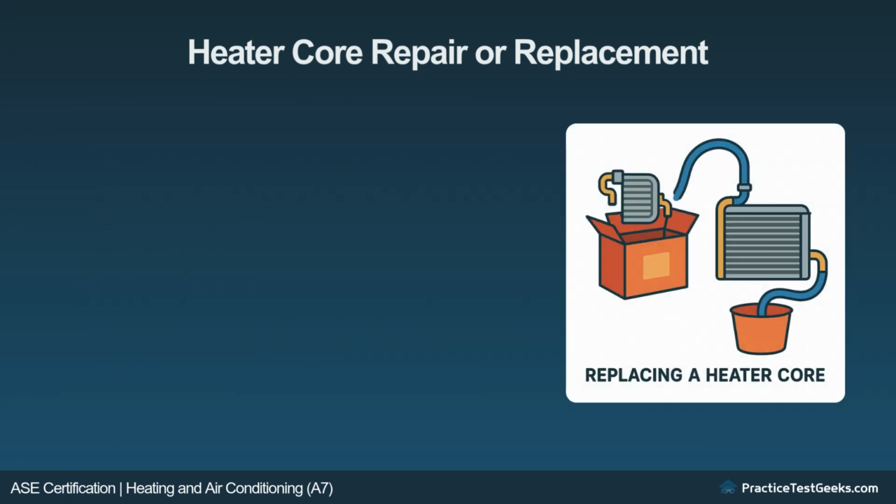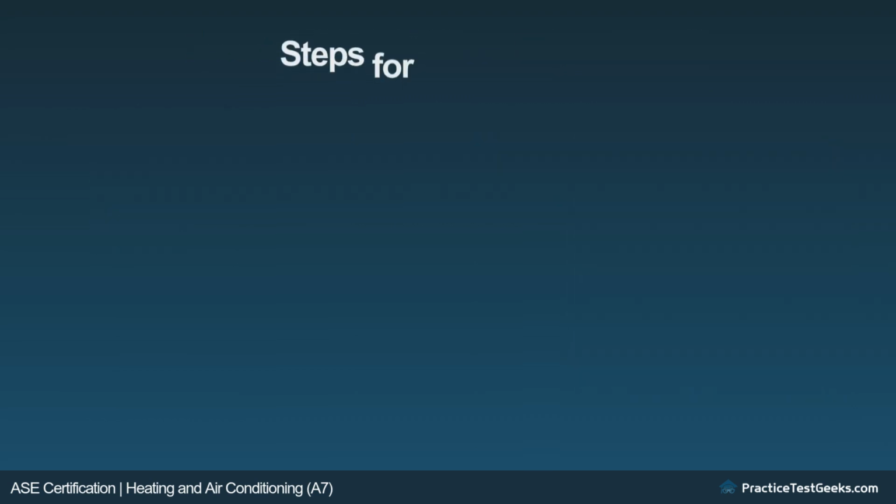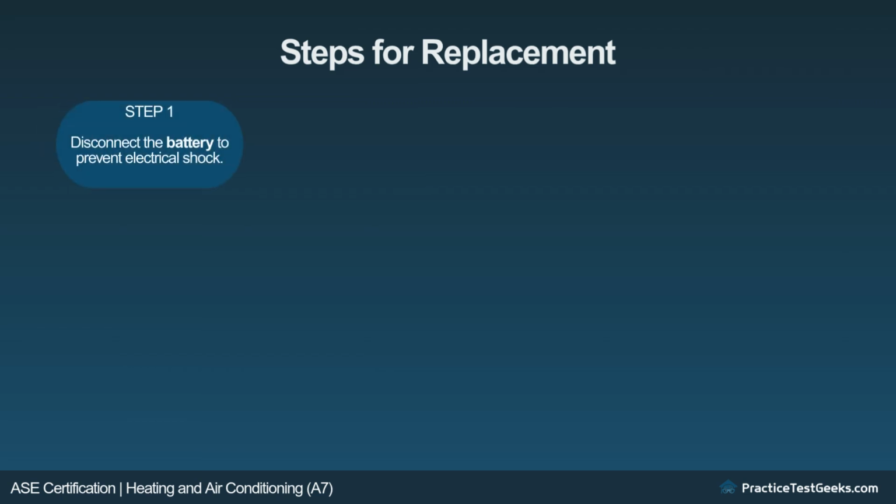Replacing a heater core. Replacing a heater core is typically more complex and involves removing parts of the dashboard or interior trim to access the core. Steps for replacement. Step 1. Disconnect the battery to prevent electrical shock. Step 2. Drain the coolant from the radiator and hoses.